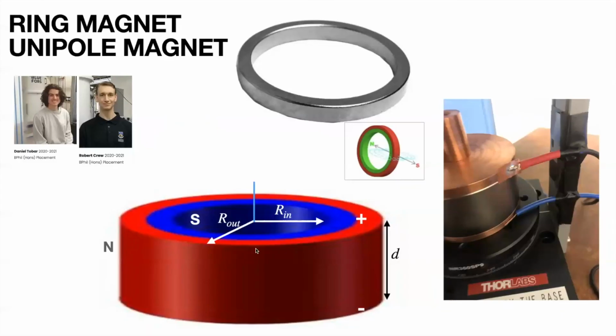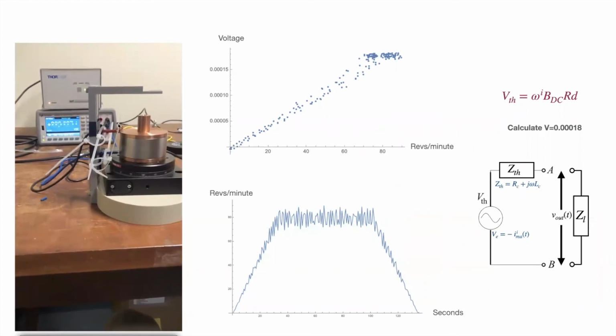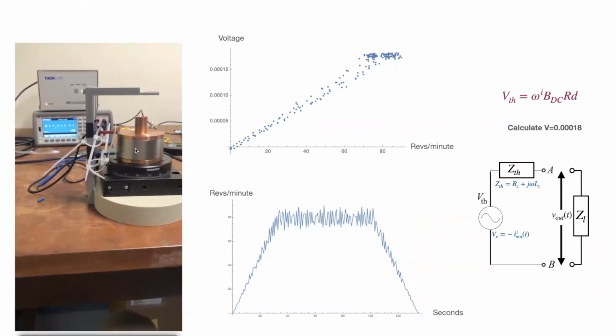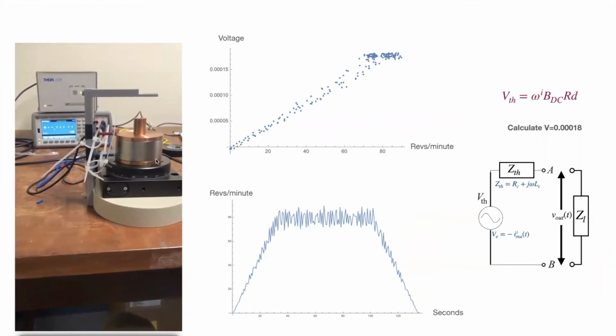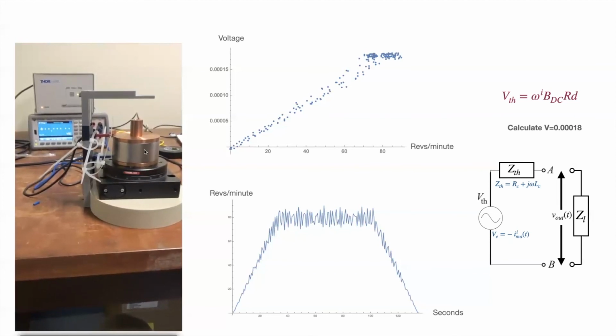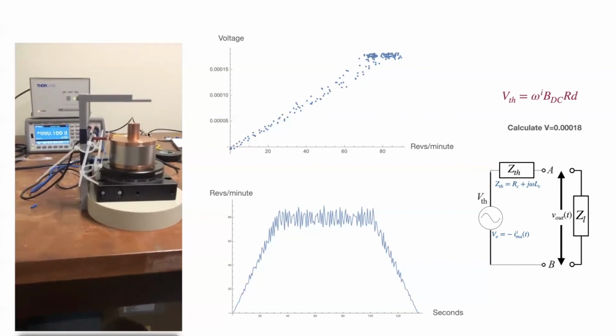It's also a spun, radially charged magnet. If you put a wire outside while it's spinning, it creates no voltage. But if I move a wire with respect to the magnetic field, it does. So that's one of Faraday's paradoxes. The wire there will have no generated voltage, and that's because there's no change in magnetic field. As this spins, because it's symmetric, the magnetic field remains constant around this magnet.